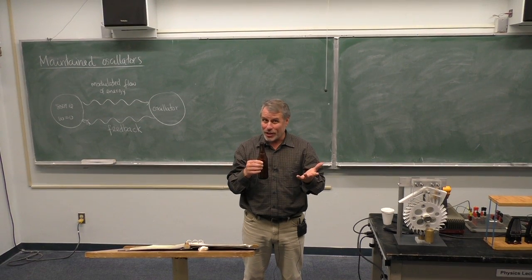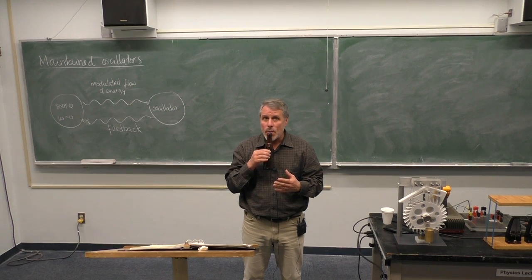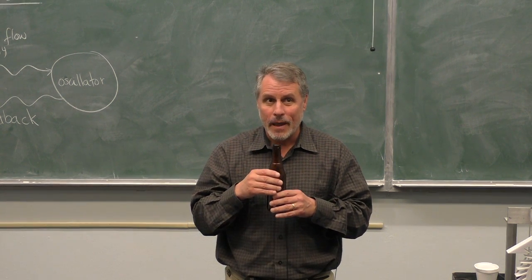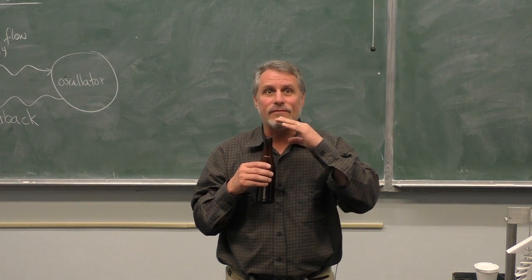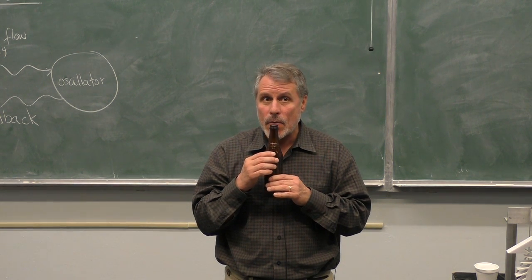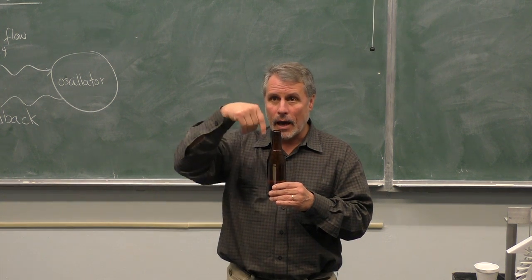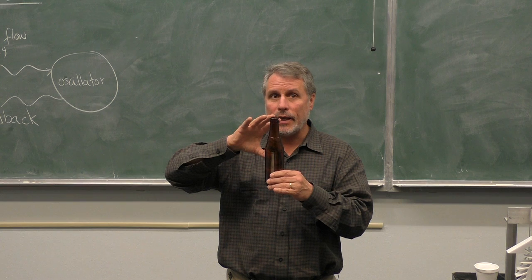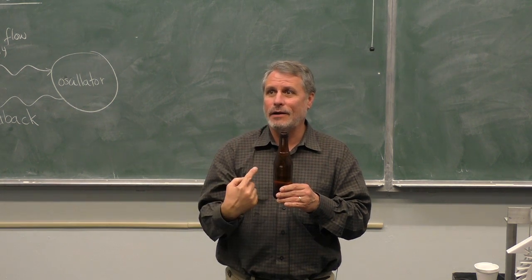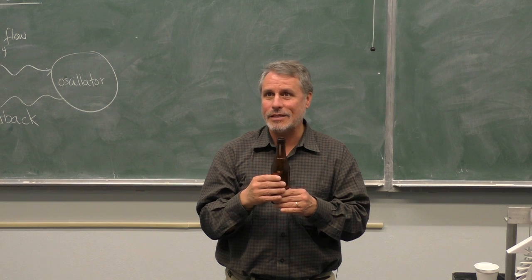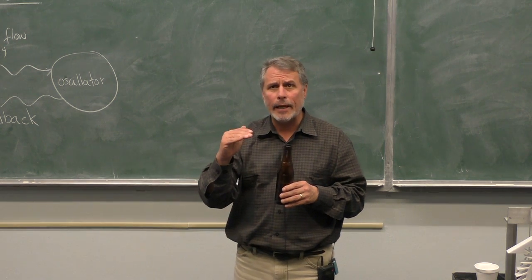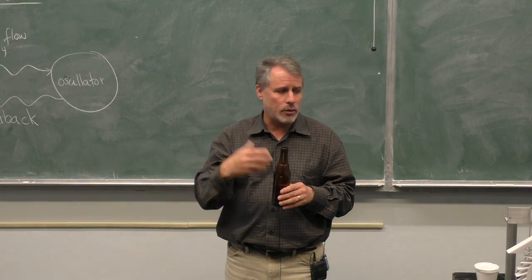sound, which is clearly an oscillation, by blowing into the bottle, and the blowing part is clearly not an oscillation. I'm not making the flow of air from my mouth through the neck of the Helmholtz resonator oscillate. But the interaction between the flow and the natural frequency of the oscillator modulates the energy flow to the oscillator as the oscillator feeds back into the source that is producing the flow, which in this case is my mouth. So there is a very active interaction between a source that does not oscillate and an oscillator that has a particular frequency of oscillation.